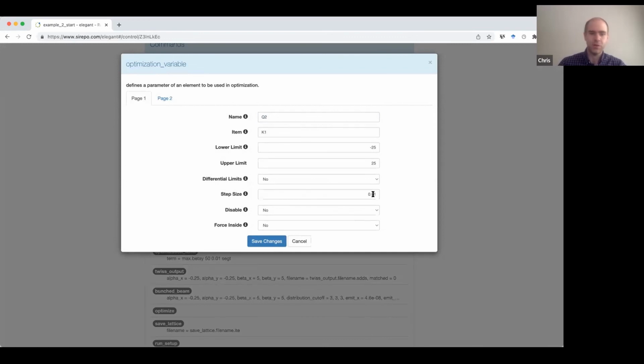If you set this really small, even though it does get varied eventually, you may find that if you don't have enough total evaluations available to the optimizer, it may not make much progress towards finding a minimum. Whereas if you set it very large, you can get very strange things happening where the optimizer will stop prematurely. So it's something to keep in mind, especially if you're looking at values significantly larger or smaller than the default of 1 here. That can be a good thing to change if you aren't seeing convergence.